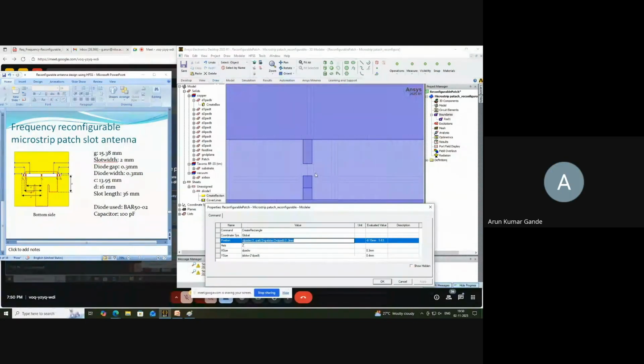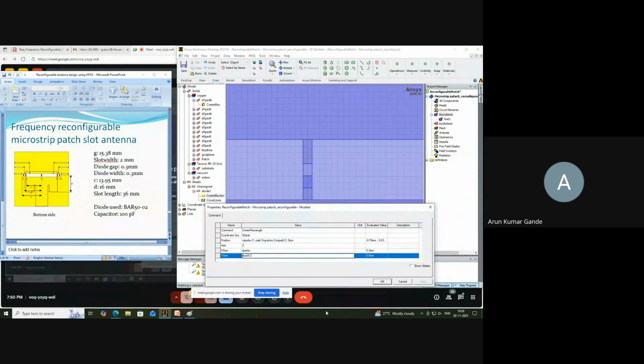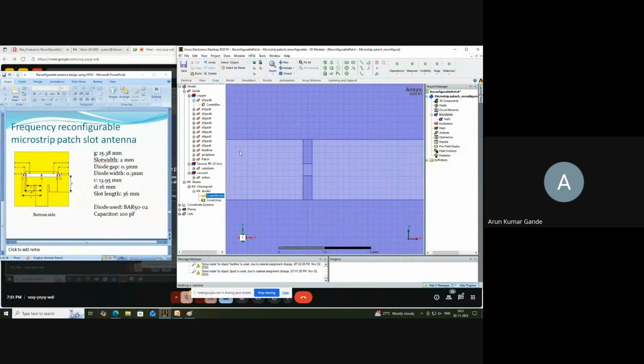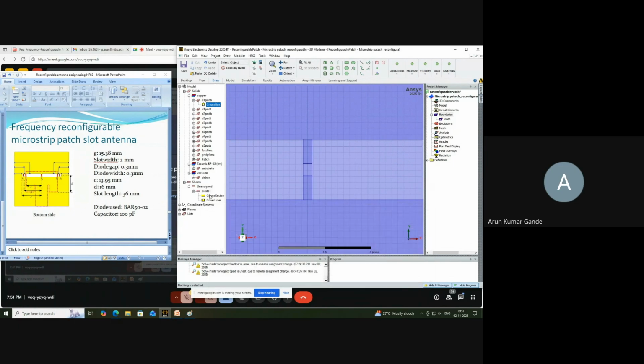So pad L minus G divided by 2 plus d pad L divided by 2, and this would be d pad L. What is happening? I made some mistakes there. So this is d pad L, moved here. I have put my diode pad here. What I've done is I've taken the dimensions here and then I've added d pad L to this dimension, and whatever gap is there, that gap I've put here, right? So accordingly,